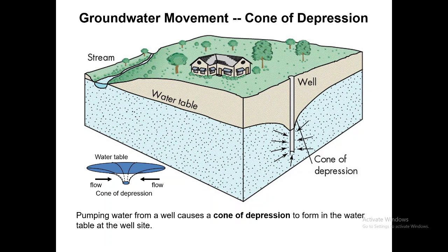And this is something about the cone of depression, which is obtained while the water is being drawn and water is being discharged. When water is discharged through a pump, especially heavy pumping, we are normally getting this kind of cone of depression. So the water table level in this area is going to reduce to this much level because of the excessive drawing, the withdrawing of the water from this well. So higher the pumping rate, the deeper this cone of depression will become.